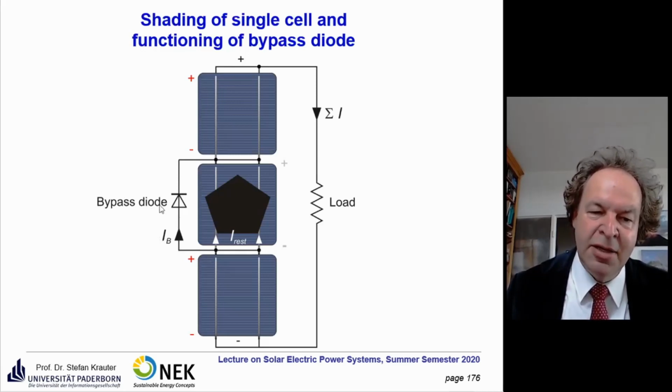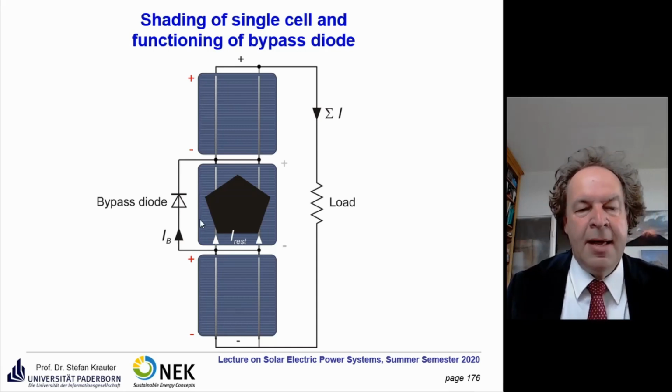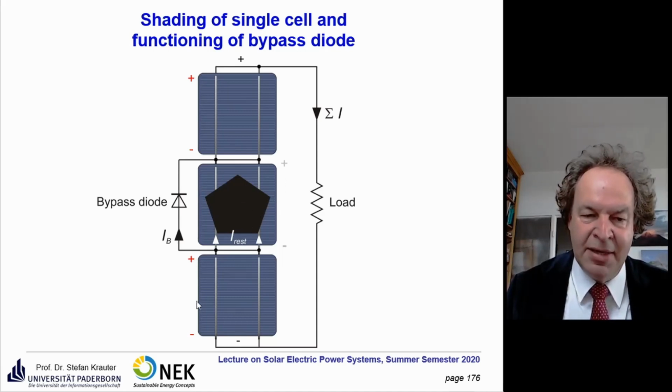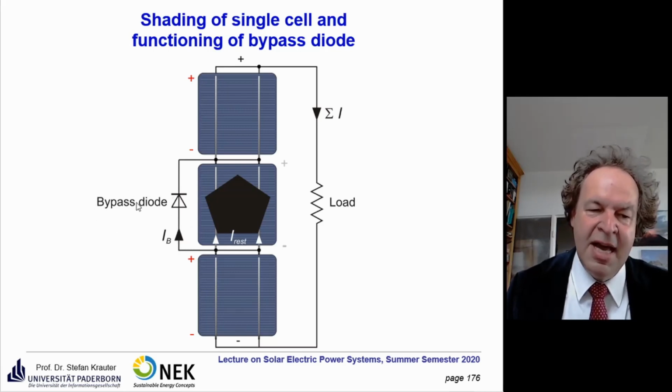So you put a diode here, so-called anti-parallel, not in parallel, but with a different direction. So the diode is looking in that direction. So here you have the cathode, and here you have the anode. The solar cell is vice versa here. And what happens, so if you have normal conditions, take off that leaf here, then you have plus, minus, plus, minus, plus, minus. What happens here, so we have plus here, minus here, nothing happens to the bypass diode. If it's a good bypass diode, it's in blocking conditions and it doesn't let pass any current here.